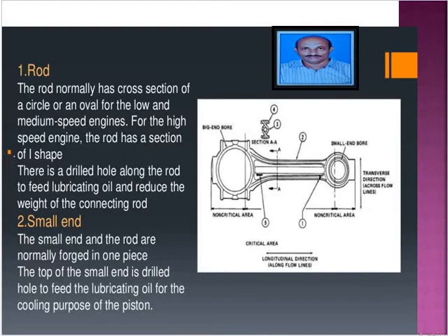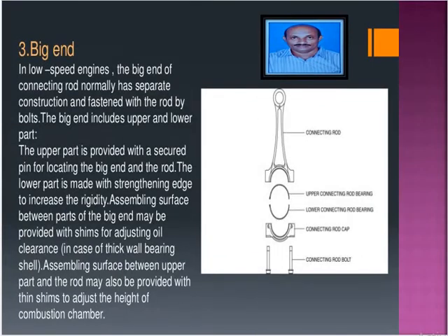Now, the connecting rod is usually manufactured by drop forging. This drop forging process gives adequate strength, stiffness, and minimum weight.